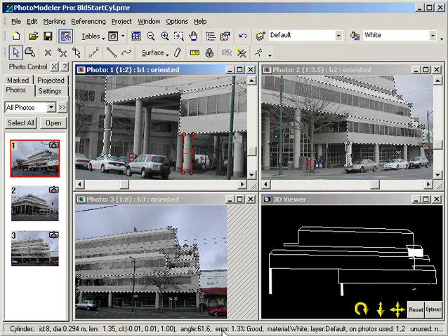We get an estimate of the cylinder error. This is similar to a residual. It provides a good rating at 1.3%. A rating of 2% or below reflects a strong result. A rating around 3% is acceptable and might improve if referenced to additional photos with strong angles. The status bar also displays the material, layer, and which photos the cylinder appears on. We have now learned how to use the cylinder tool. This tool is useful for creating more complete models.